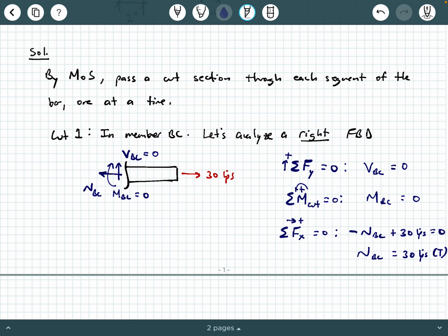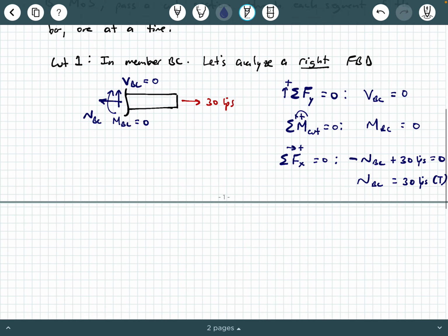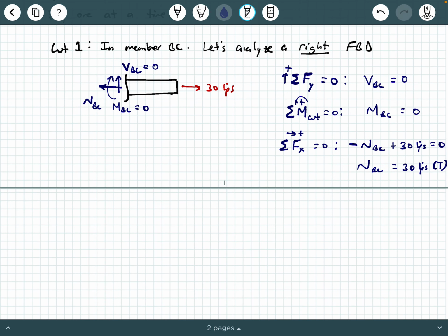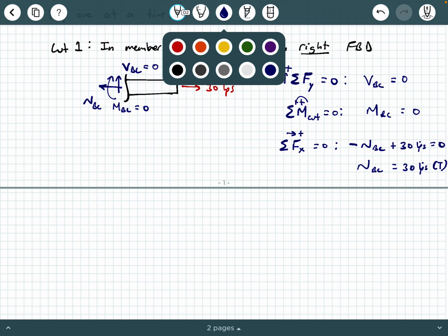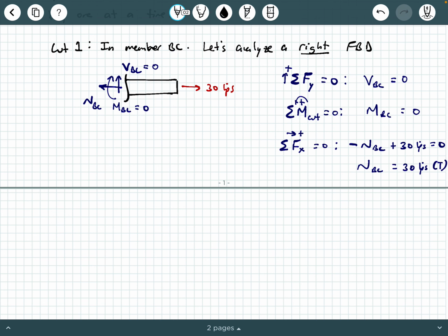This is statics, all right? But this is just a review. Okay, are we done? No, we have two segments here, so we need to make another cut, okay? I'm going to say cut 2, and we're going to cut this one in member AB, okay? And then I'm also going to say the same thing. Let's analyze a left free body diagram, okay?